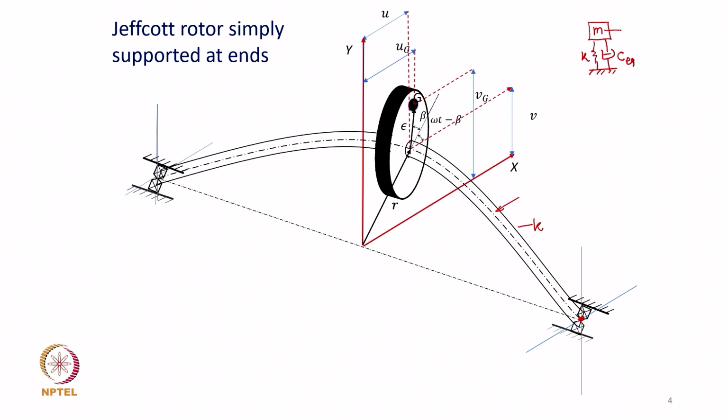Now, this mass is what? We typically say x dot and x double dot, x is the degree of freedom. Now, in this case we are going to work with, because the disc is going to rotate like this, I can imagine that this shaft or shaft center is going to move as the rotor spins, and it is going to move up, and then it is going to actually whirl around the bearing axis.